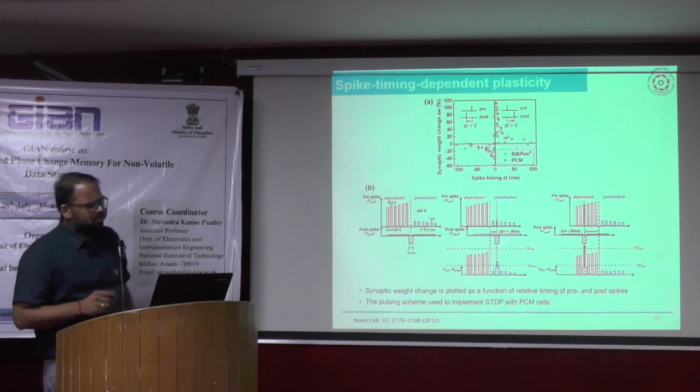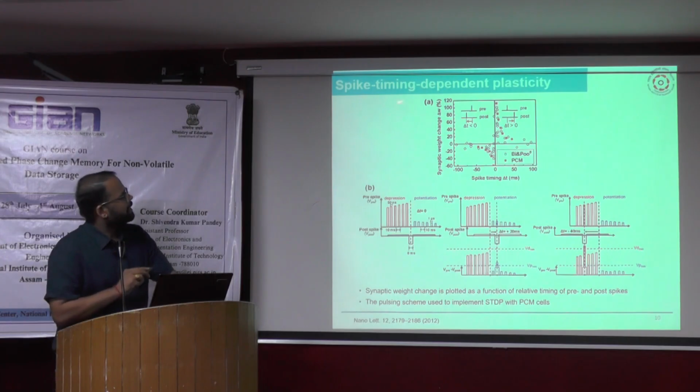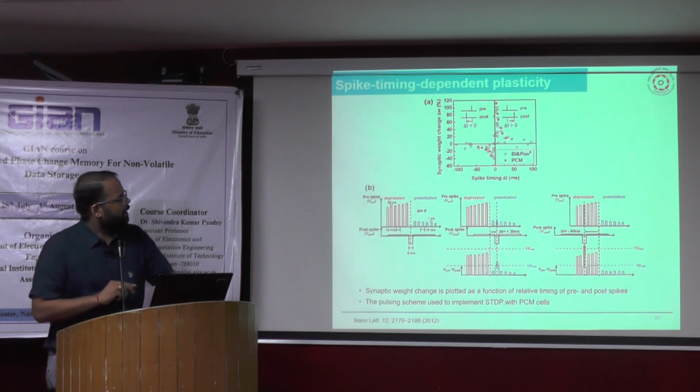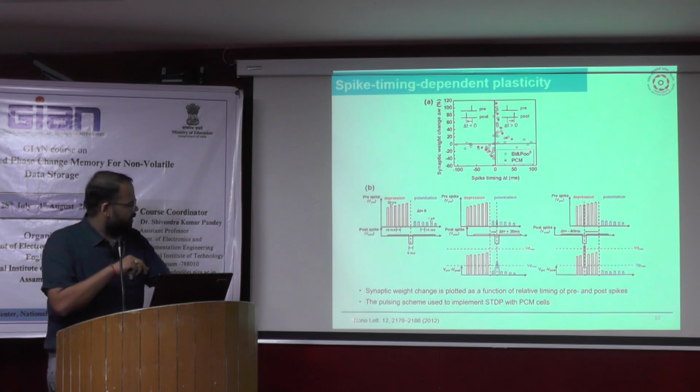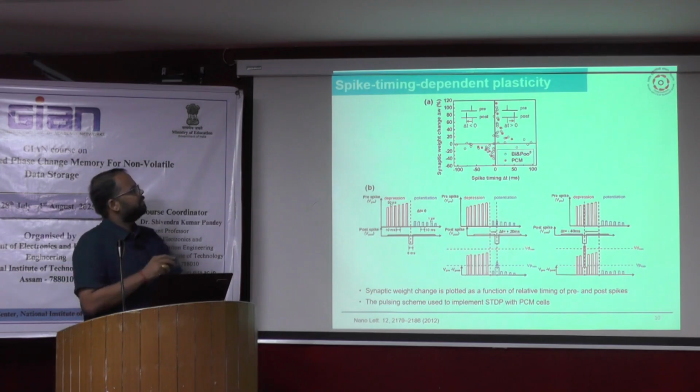If we talk more deeply about neuromorphic computing, spike-time-dependent plasticity is very important for identifying the goal of neuromorphic computing in the case of a PCM device. In this reported work, they tested the time-dependent weight change.